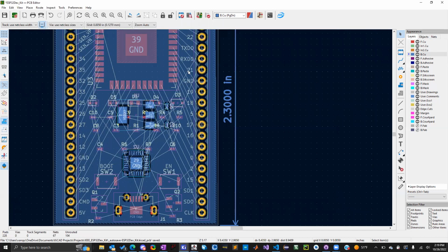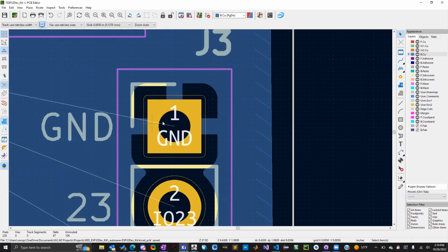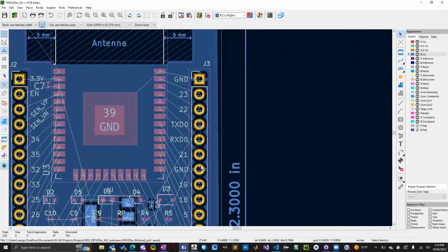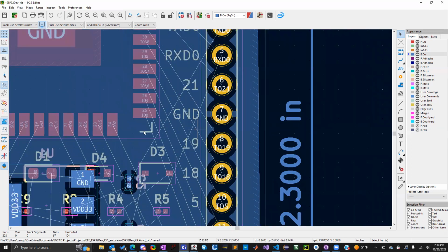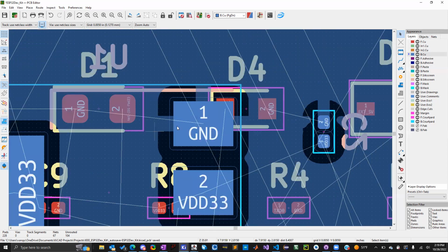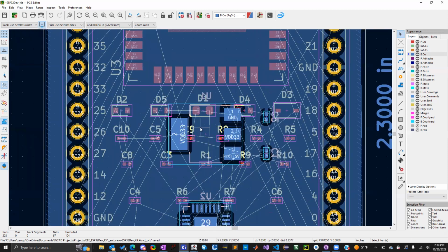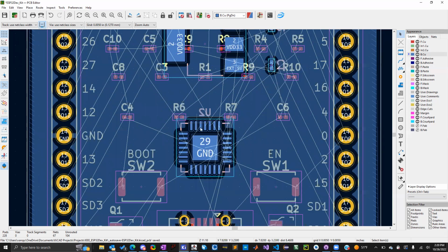And then you should see on all your ground connections on the through hole components, these are the thermal vias I was talking about here. And then because of the minimum clearance, there's no ground in between the vias, so we can't put a thermal relief on that fourth corner. And then same thing for pins in between, they only get the two sides, which is okay. So all your ground pads will have thermal vias as well. Not as important. Well, it is important still for pads, but we're going to have the manufacturer do it, so we'll be okay.